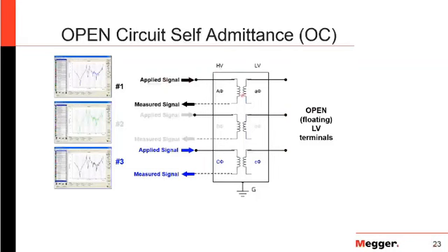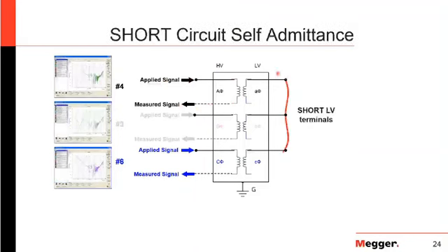Apply a signal to the A phase, and then measure on the opposite part of the winding, and then do the same thing for the B phase and do the same thing for the C phase, and just have the low voltage terminal shorted this whole time. And generally what a lot of people do in practice to make it quicker is I would start with A phase and have my leads connected here and go apply here, measure here with everything floating, nothing else connected.